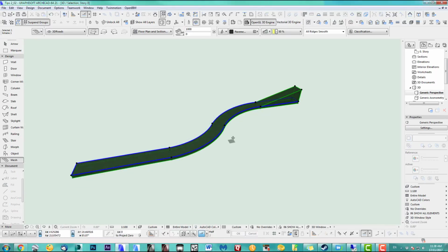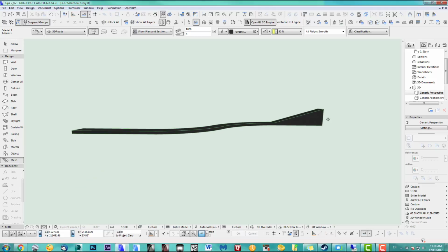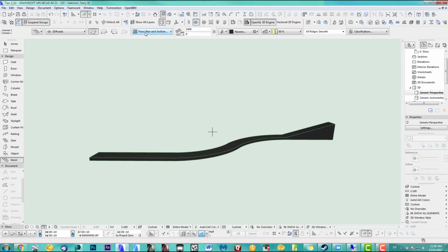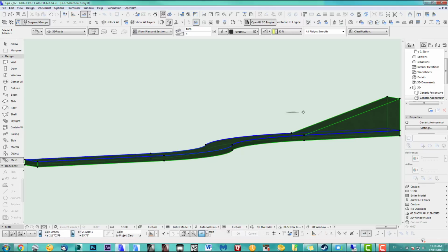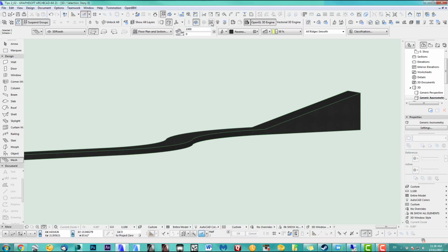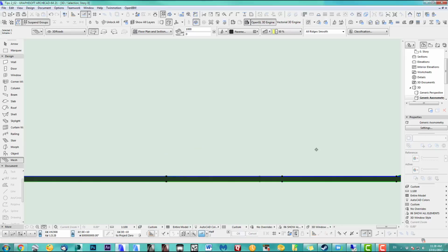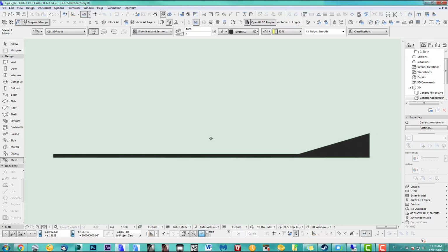All right, so how do we get this nicely sloped all the way down to 0? That's a very simple trick. You go from the perspective view into the isometric view, and then you use this tool here, which looks perpendicular to the clicked surface. So I click here, click on the side, and now we're looking at this side on.